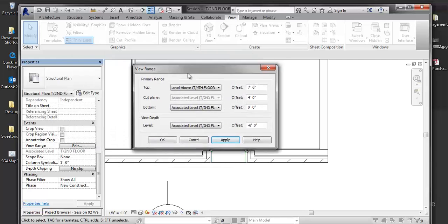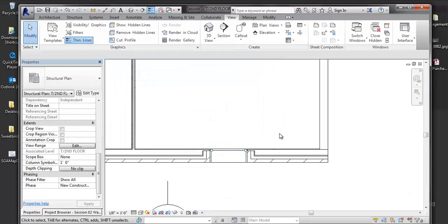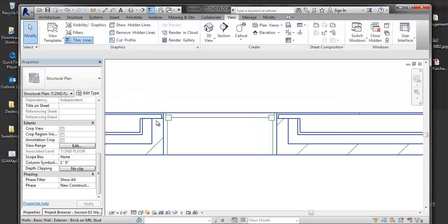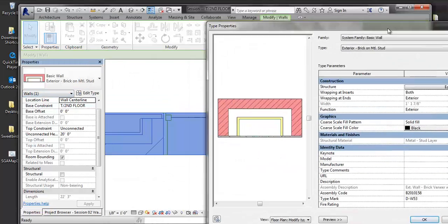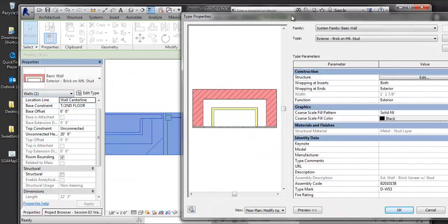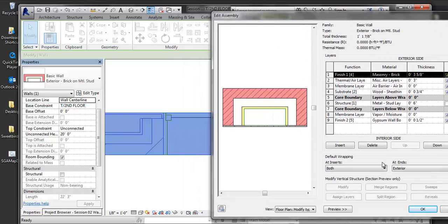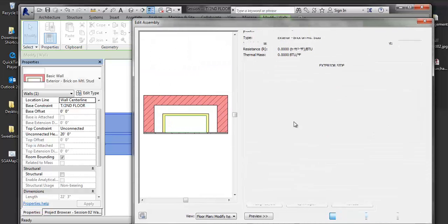So everybody got this matching? Okay. All right, so again, looking at the insert now. So I've come in and I've put in a wall or a window. So that is designated as insert. Because if I go to edit type on my wall now, on my assembly here, and edit the structure, because I've decided that both handle that inserts, you'll see that the gypsum wraps as well as that exterior wrapping to the inside. If I chose it to only wrap as exterior, and I click apply,